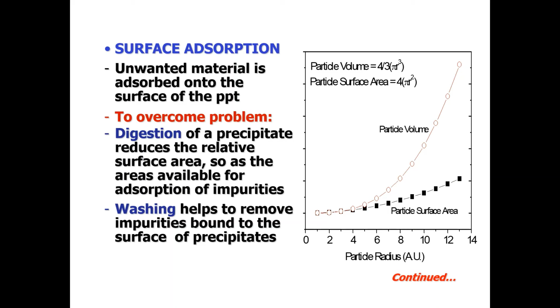Now, how can we overcome or remove the impurities? The first is always by washing, because we can wash by spraying dilute electrolyte onto the surface. We are trying to remove the adsorbed layer, meaning those ions trapped on the first layer, and also the ions on the outer layer, the second layer. The second layer is very easy.